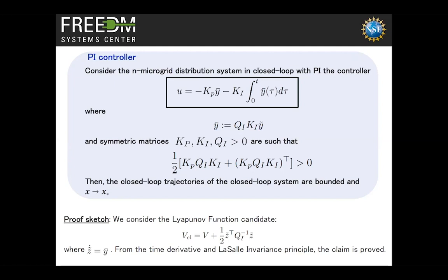Right, okay, so here is the multivariable PI controller where the Y bar again is not the absolute voltage, it's not the absolute output, it's the output measured with respect to what I had in the previous equilibrium. So you have a proportional term and an integral term, but you have to remember that because this is multivariable, the Kp and the Ki are matrices. These are not just scalar constants anymore. They are matrices, which means that the zero pattern or the sparsity pattern of these matrices decides which converters have to talk to each other. If these are dense matrices, that really means that I need all-to-all communication from other converters to compute my control input. And if I can somehow promote sparsity, if I can promote some of the entries of these Kp and Ki matrices to be zero, that means that I don't need feedback from those other inverters to compute my control gains.